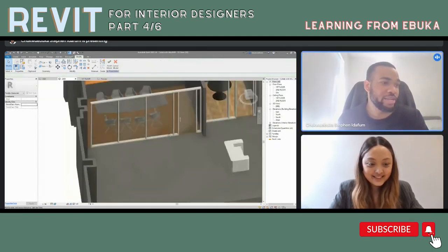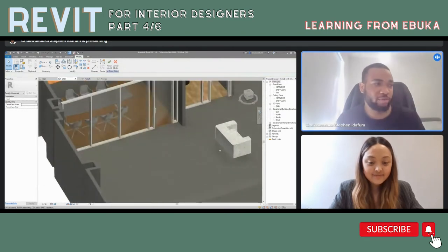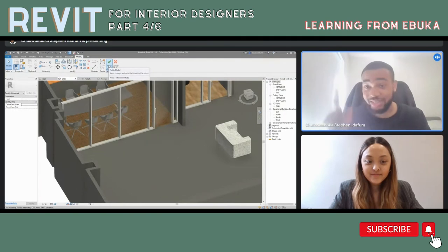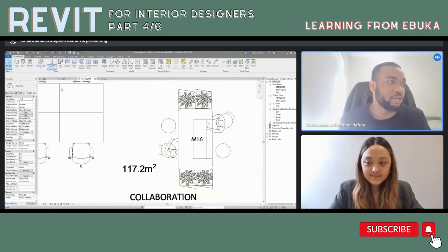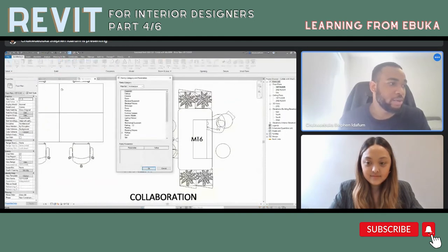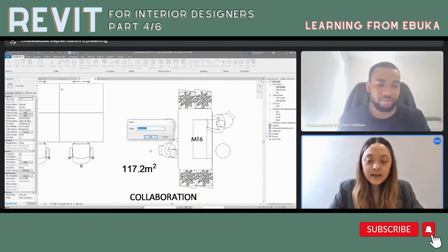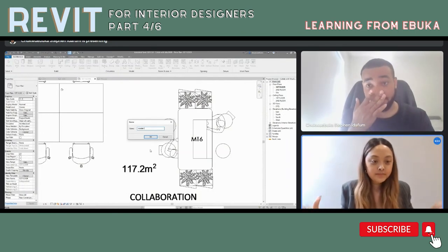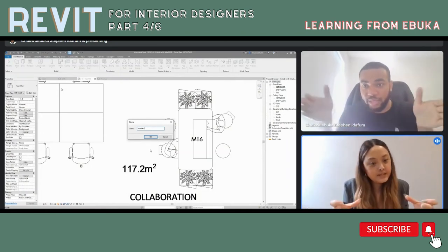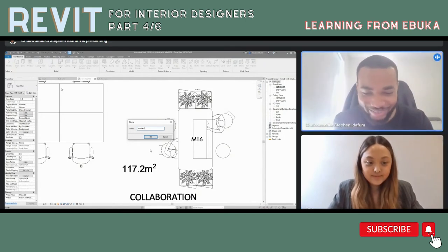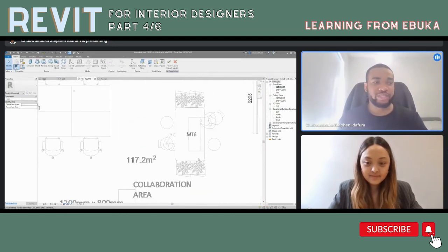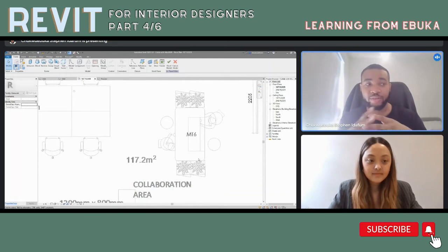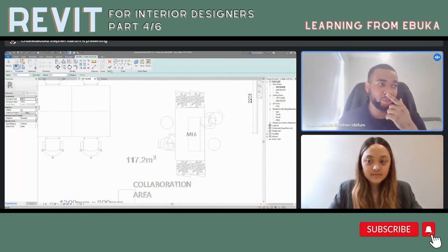So now we need to do the under part, the wood material part, sorry, the timber part. Same thing. Go to your floor plan, go to architecture, components, model in place. Still casework. I want to make it a little bit offset from the actual volume, so the bottom part is a little bit smaller. So, base, wooden base. Press OK.